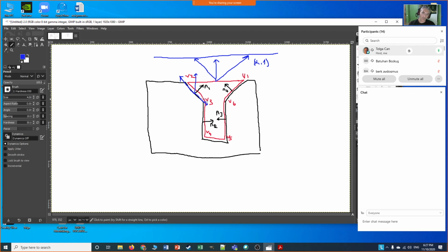So I can pull in all directions in between these two, and that will be safe. If the angle between the normal of this mold and the pulling direction is more than 90 degrees, then this will block the pulling direction.